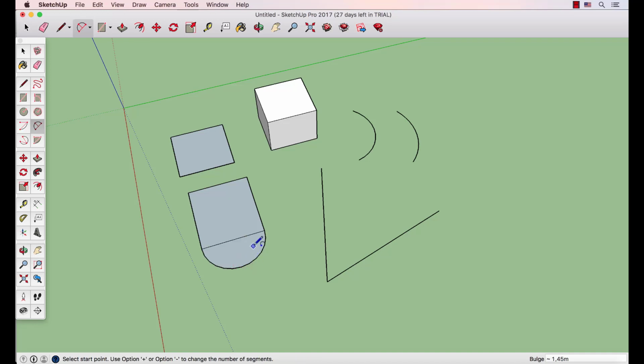With this tool, we can also design an arc tangent to two lines that form an angle between them. We begin by clicking on the point of the first line, then place our cursor on the other line of the angle, and by moving it along the line, we can find the point that we have to choose so that the two lines are tangent to the arc that will be formed.